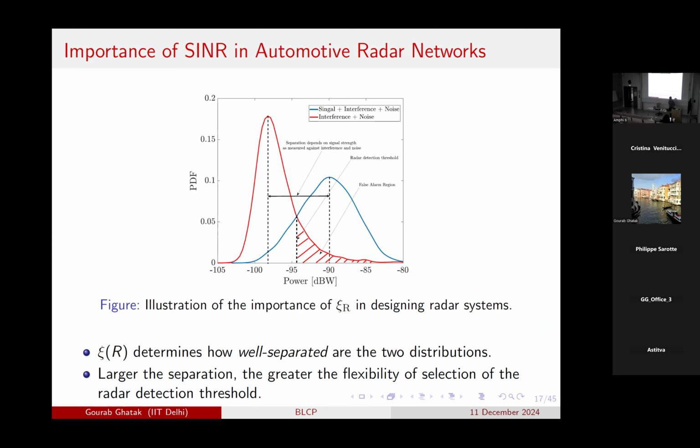Yes. So we tried to do it for the detection. It's difficult. Basically you are asking what is the CDF of interference. So the probability that signal plus noise plus interference is greater than a threshold. Let's say if I remove noise, the misdetection is the probability that interference is greater than a threshold, which is the CDF of interference. Then you again need the Gil-Pelaez inversion theorem and things like that.